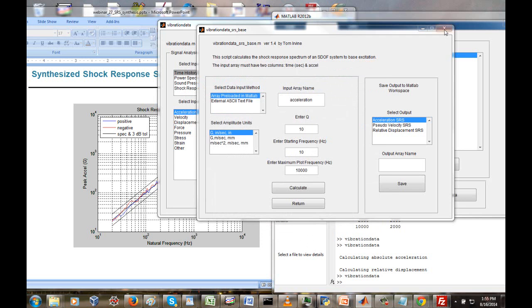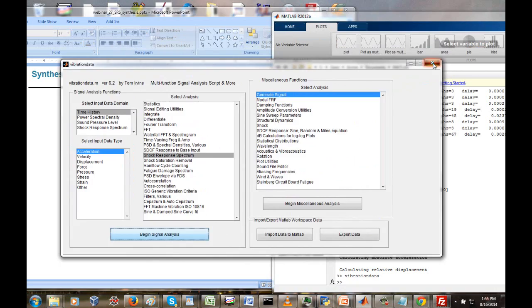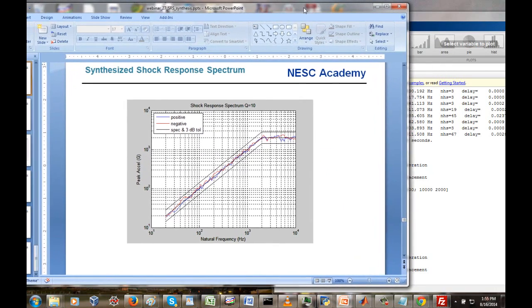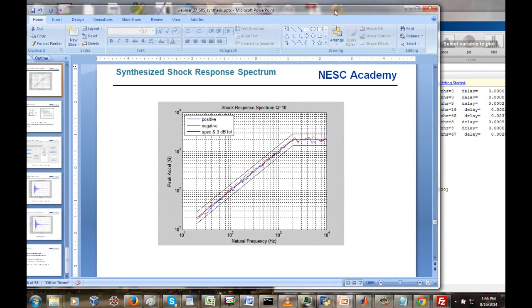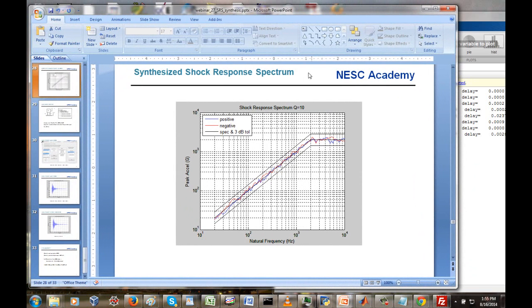So I hope you've enjoyed this, well, I said process. It is a process we went through today. Just a couple other notes, and we'll be talking about this in future webinars. There are ways within finite element packages to directly input an SRS and calculate the response. And that uses some approximation techniques we'll talk about later. There's a Naval Research Laboratory method, which is just one example.